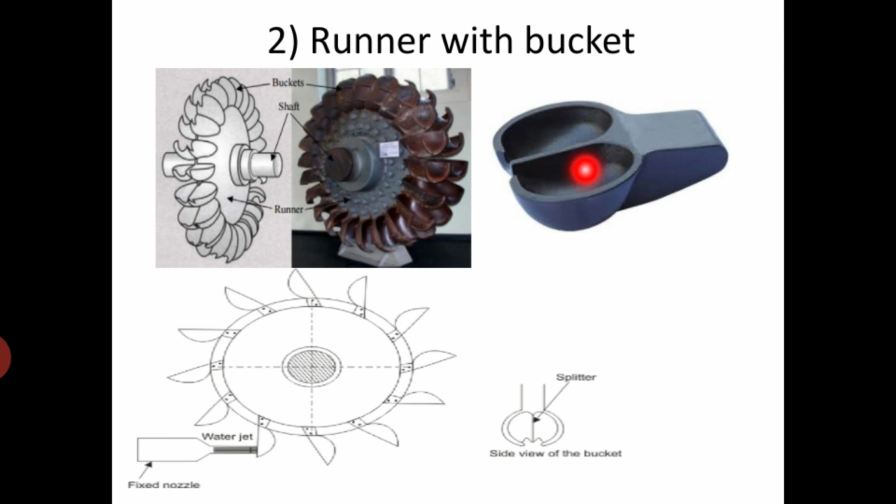The advantage of having two spoons lies in the fact that the axial forces, that is, forces perpendicular to the direction of motion, neutralize each other, being equal and opposite, and hence the bearings supporting the wheel shaft, that is this one, are not subjected to any axial thrust.